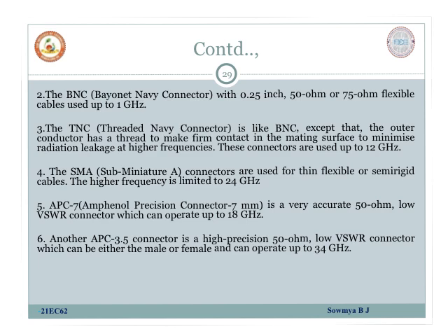Next we have BNC connector, Bayonet navy connector. This is having a dimension of 0.25 inch and the impedance is 50 ohms or 75 ohms and it is a flexible cable which is used up to 1 gigahertz.